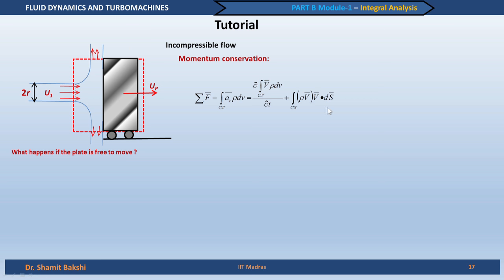This is what we derived while we derived the expression for the force in the case of a non-inertial frame of reference, not in the general form, but for a control volume moving with a linear acceleration. So, this is the extra term which comes there, which is basically the inertia force acting on the control volume. So, acceleration of the control volume, rho into dv. The small v of course is the representative of a volume, not of the velocity. We have to keep that in mind.